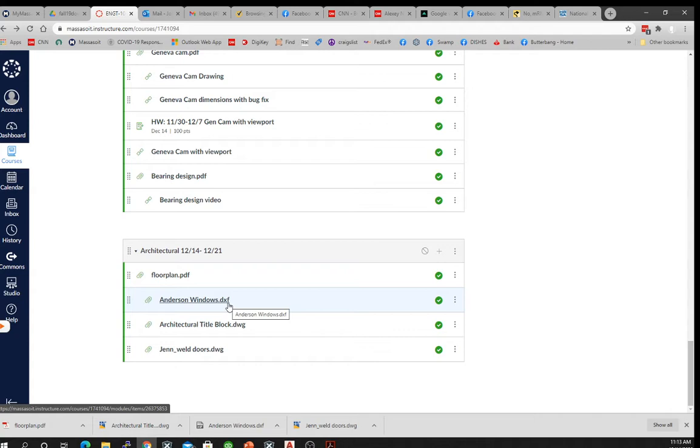While most CAD systems can automatically read AutoCAD formats, AutoCAD can't necessarily read and open every other CAD system. But virtually every CAD system can open and read a DXF. So DXF is kind of like a universal translator format. Every CAD system should be able to open a DXF.